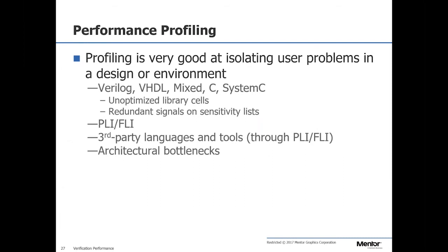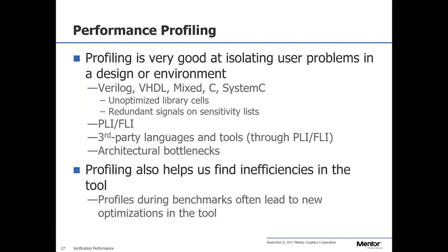So once you've got that baseline, now we can use this thing called the profiler. What the profiler does is it samples, about once every 1,000 simulator steps, maybe, what line of code is being executed at this moment. So now if you run your simulation for a few million clock cycles, you end up getting a profile that says, where is all my simulation time going?